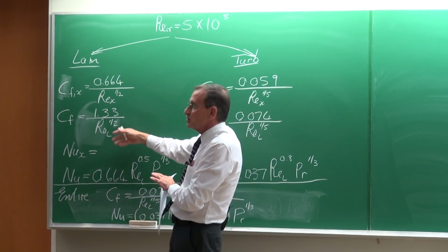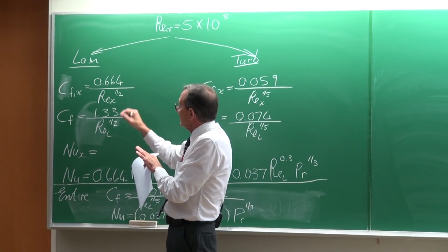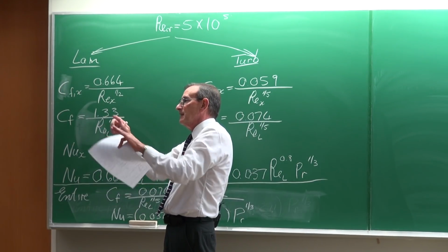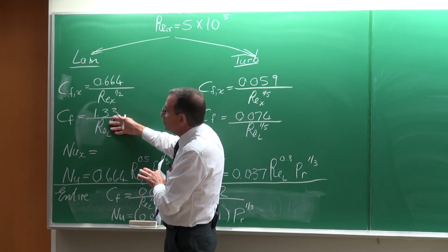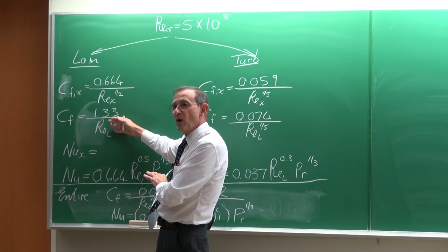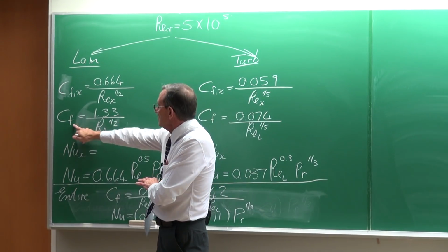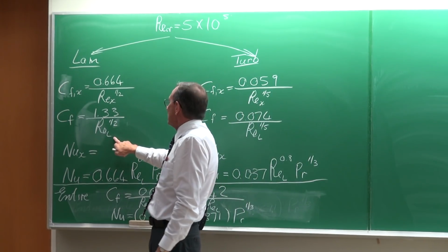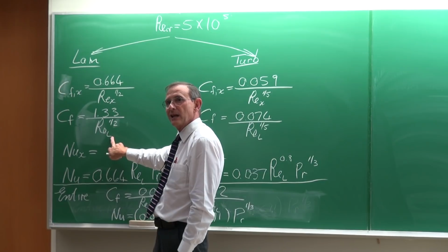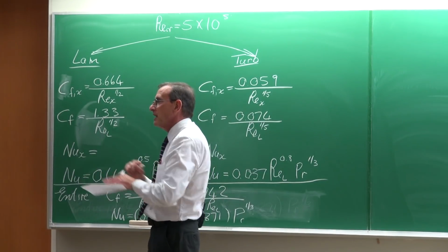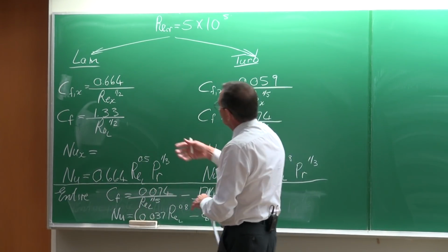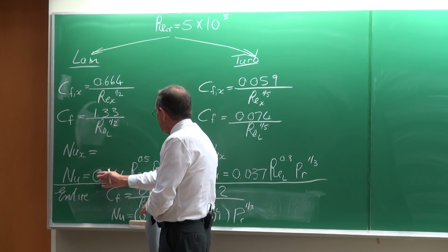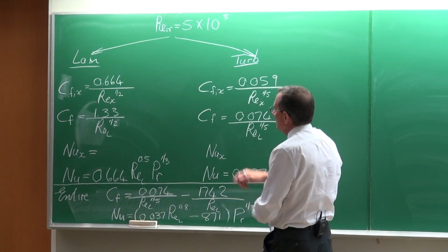We as engineers do not want to go and calculate it at 10 or 20 or 100 points over a flat plate and then do the integration. We would preferably want to work with one value, and this would then be the average value over the length of the plate. That is why it is the Reynolds number based on the length of the plate.